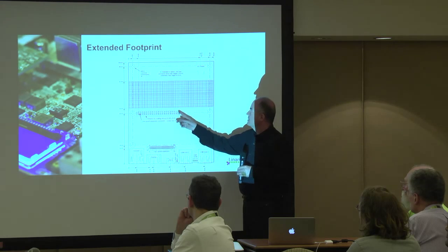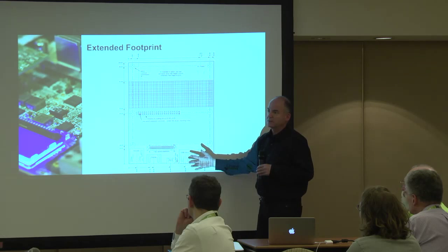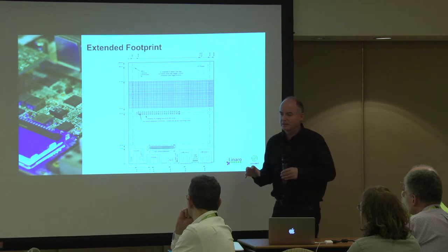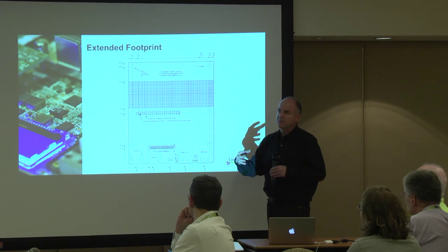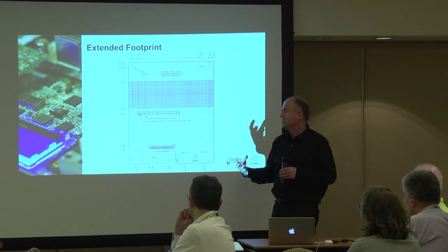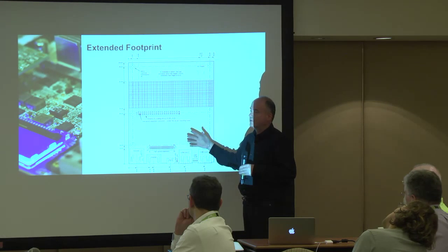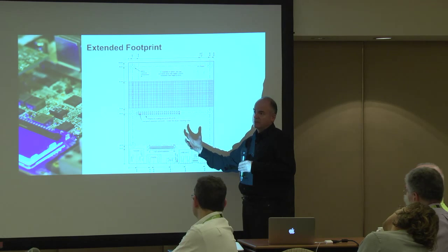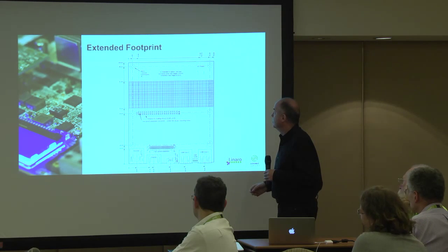And because this connector can be surface mount, you can actually create a lot of space on the bottom of the board. So we've got some users who basically, rather than using a single LPDDR RAM, which would be a 32-bit device, want to put 2 or 4 RAM devices on to get more performance. And there really isn't enough space to do that and put a PMIC and the SoC and so on on this footprint at the moment. So in that case, you'd probably design it with the SoC on the underneath and 4 RAM devices, right? Or even an SODIMM.